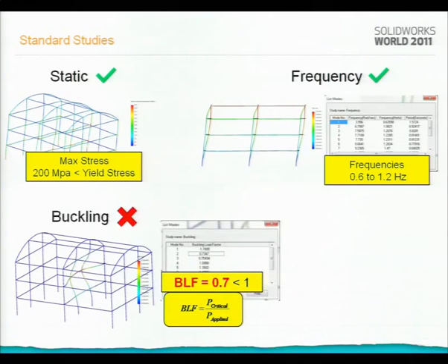About the buckling, although static and frequency analysis passed, I have some problem with buckling. The two central loads are actually buckling. How do I detect this? With the BLF factor. BLF stands for buckling load factor. And the formula is the critical load divided by the applied load.